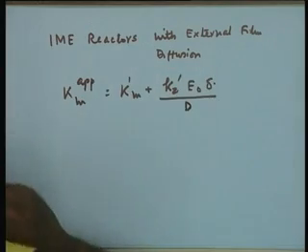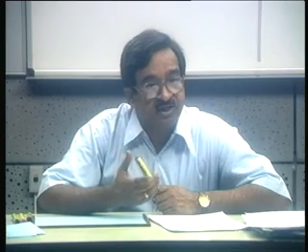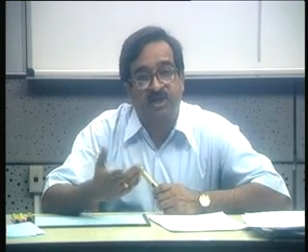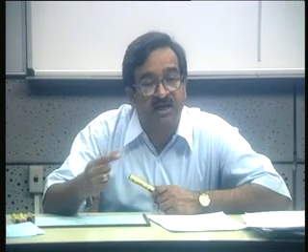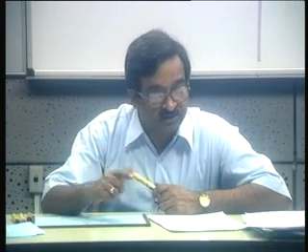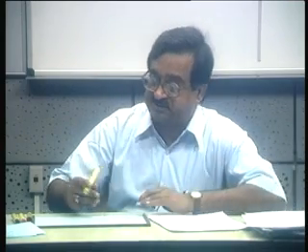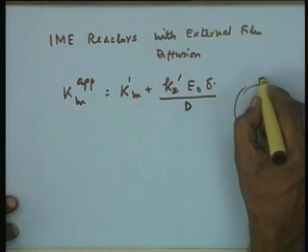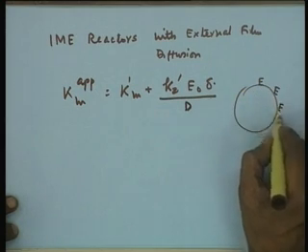Now, the problem is that experimental measurement of the film thickness is not an easy task. One cannot really, for any immobilized enzyme reactor, measure the film thickness and then make a design computation. So, an alternative analytical method has to be chosen, and I think the best way is to look at the steady state reactor performance. That means, let us say you have an immobilized enzyme particle which is non-porous in nature. All the enzyme is immobilized on the surface, a typical particle on which enzyme is only on the surface.